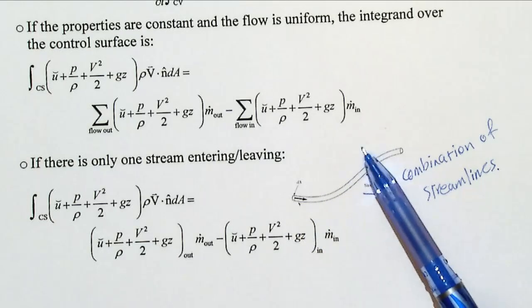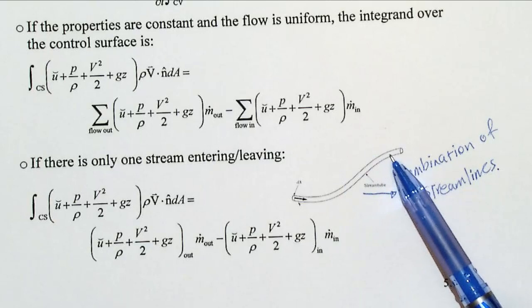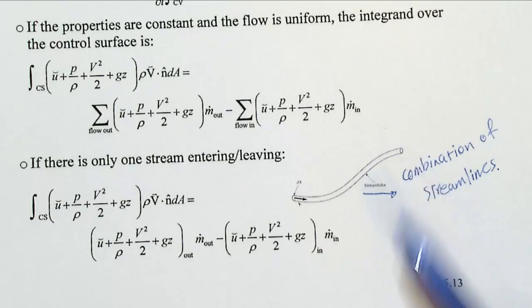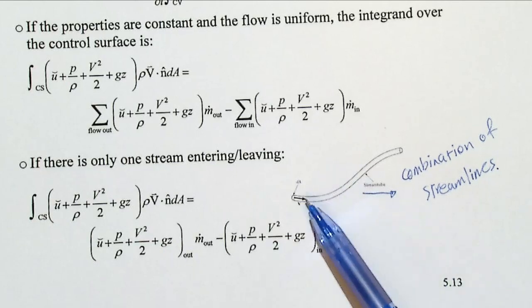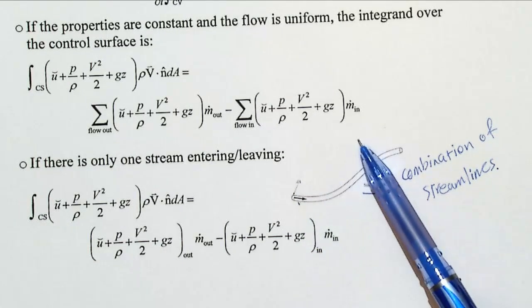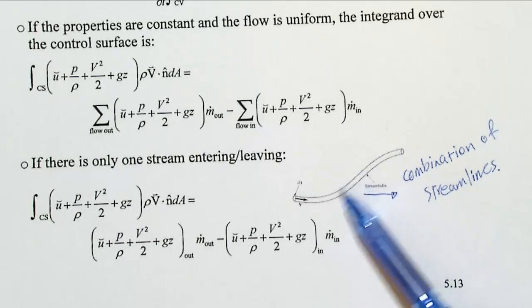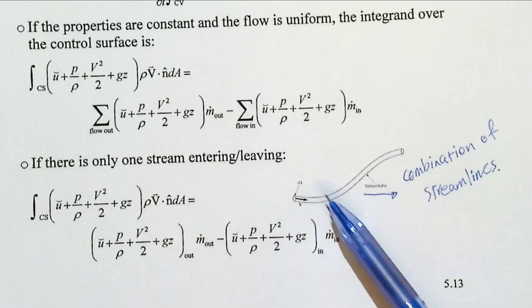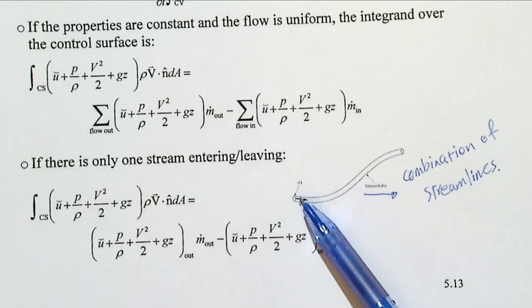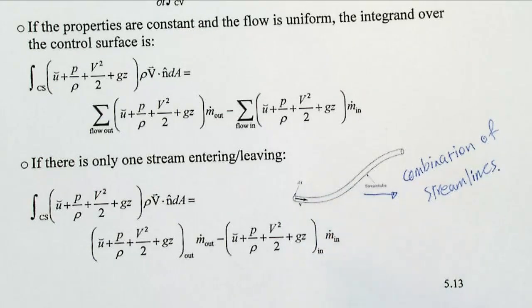They are not going out, because that's your streamline, and it passes over here, that is your output. You will tell me that maybe the particle goes there because that's a pathline, and this is a streamline. Yes, you're right, but we assume that this is a steady state. If it is steady state, then a streamline, pathline and streakline are all the same.